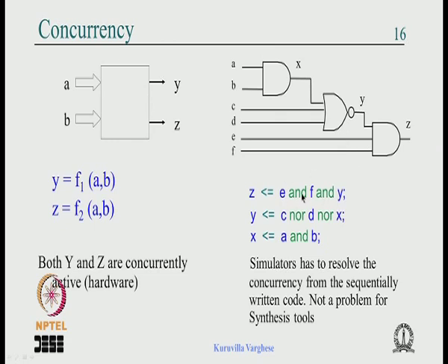It really doesn't matter in which order the code is written as far as synthesis is concerned, because the synthesis tool is worried about the structure of the circuit, not the real time behavior. But the simulator has to simulate the real time behavior and it has to worry about the concurrency.